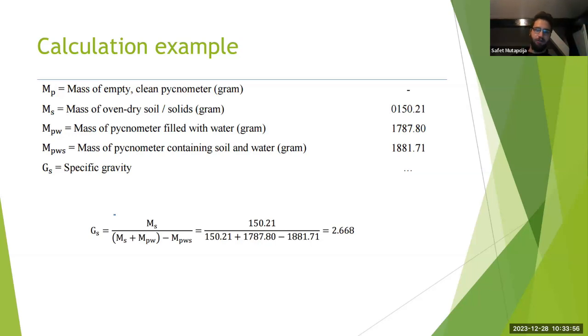So you're just going to cut some steps there, going to save something like 5 minutes, which sometimes can be important when you have really close deadlines. And you're going to get the mass of your soil, and the mass of the pycnometer filled with water, that you usually know from before because every time it is the same.